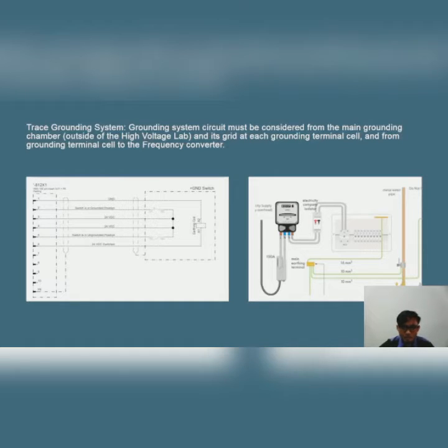Then, okay, a grounding system is the arrangement by which an electrical installation is connected to the earth by means of a conductor. This is used for safety purposes, although sometimes also for functional purposes. Okay, for example, in the case of the telegraph line, which uses the earth as a conductor to save the cost of a return wire over a long circuit.